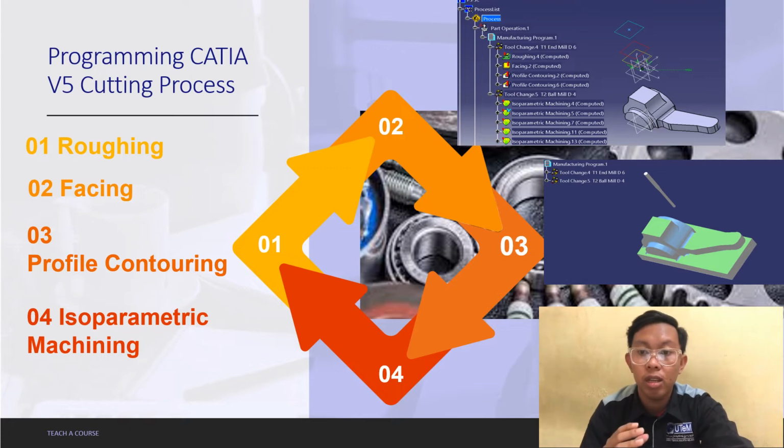The pattern is fabricated from the wooden block using two tools, the end mill D6 and then the ball mill D4, selected for the cutting process. Once everything is in place, CNC machining programming is carried out.